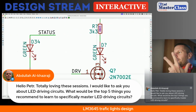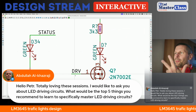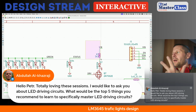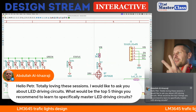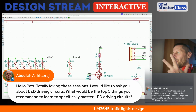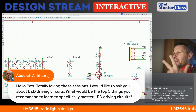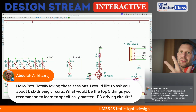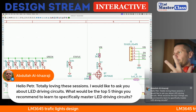So you can replace this NMOS with a BJT, but you have to place some base resistor to limit the base current of the BJT. So I can say that the NMOS driver is easier to use. To be completely precise, you have to place a gate resistor here of, let's say, 100K or something. I am editing to avoid confusion.